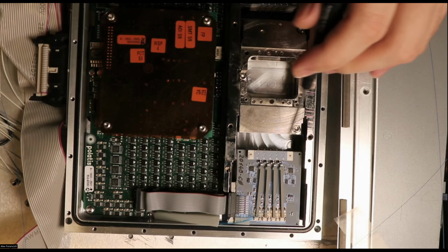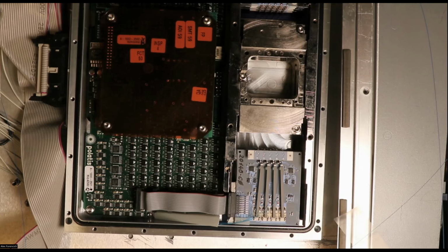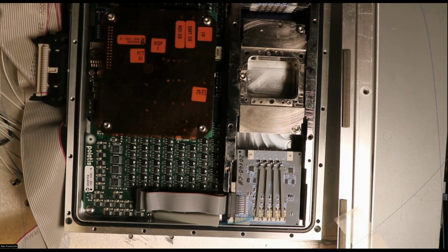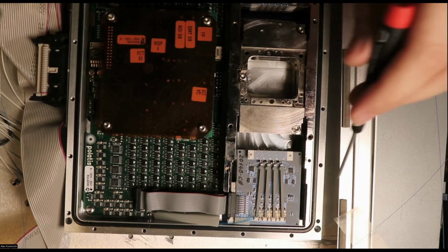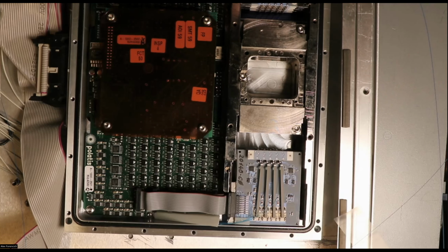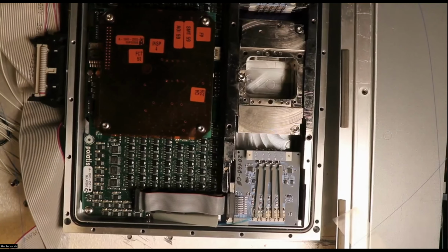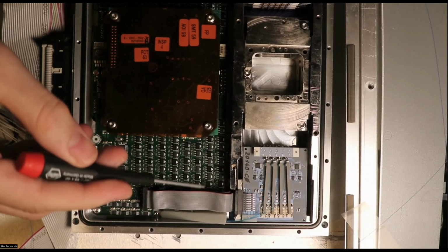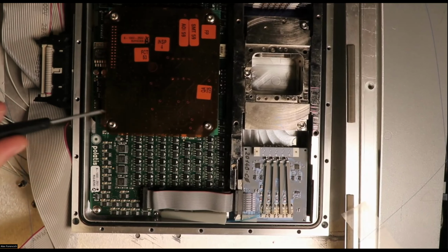So they use that to detect the position of the fiber collimator lenses, and then they have a DSP chip over here, which I guess is looking at that information and then adjusting the drive signals going to all of the actuators here. So there's not a whole lot to see, but it is a pretty cool looking unit. Although look at all of the transistors over here on the drive board for driving the actual piezoelectric actuators.